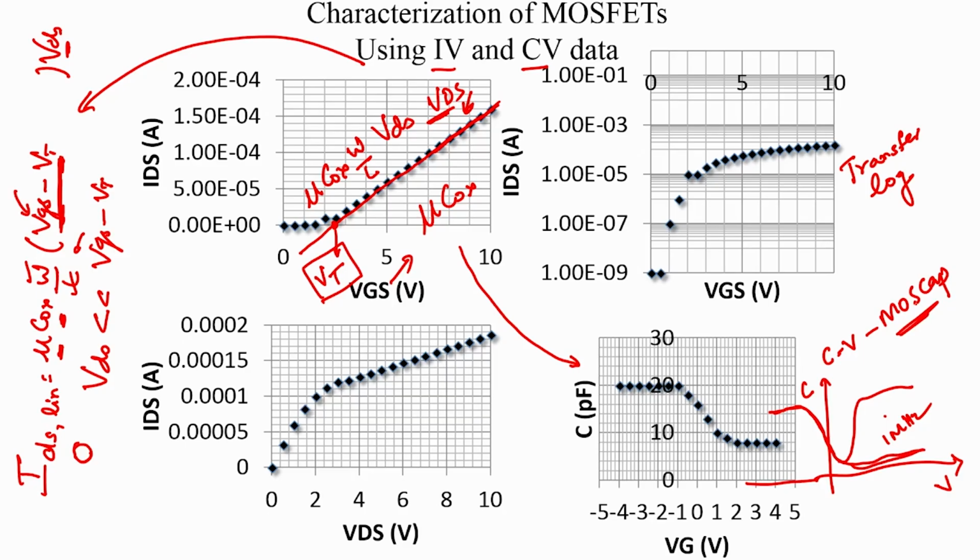But it is very likely that if you were to take a MOSFET, and perform the high frequency CV characteristics on the MOS capacitor and the MOSFET, it is very likely that at the 1 megahertz point that we still obtain the low frequency characteristics.